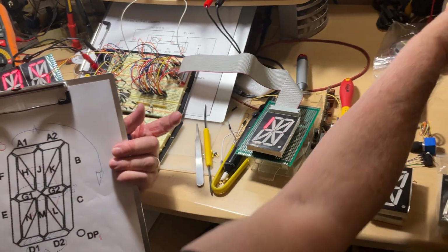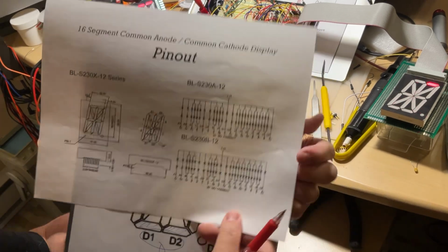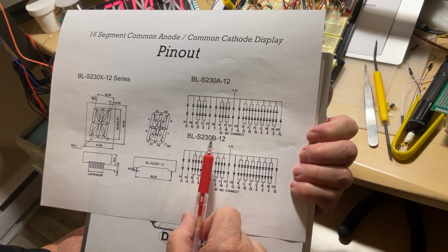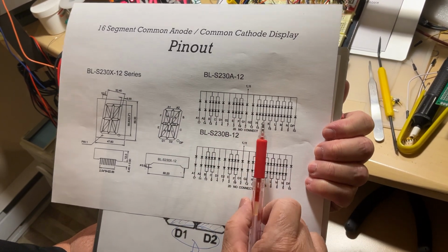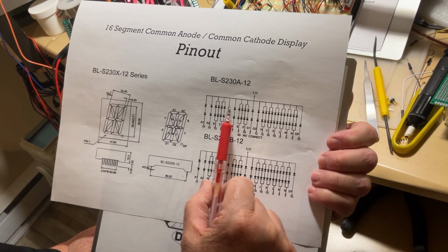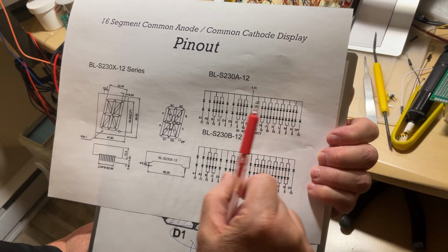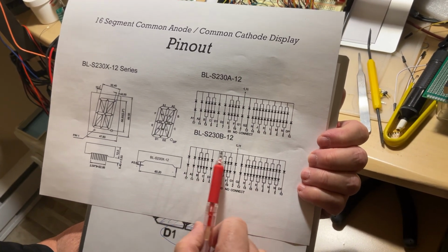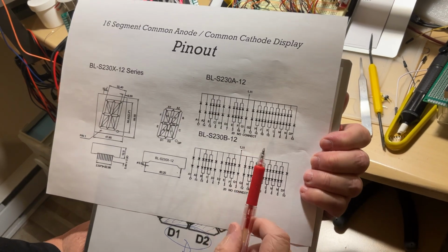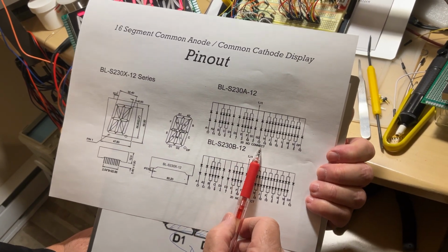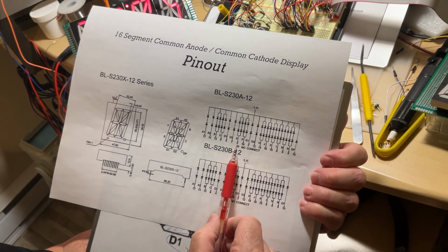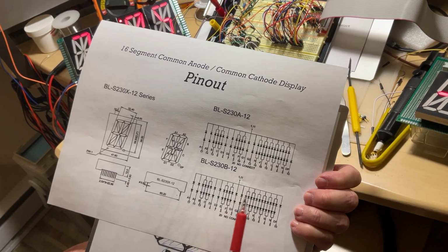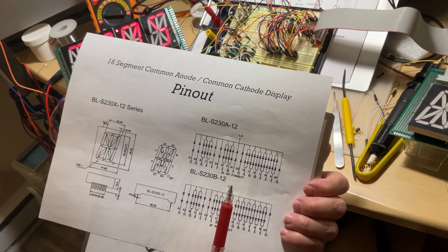And if I pick up the extract from the specifications, where the manufacturer gives us all the pin numbers, here, if you can see, all the cathodes are together. So this is the common cathode version. And here all the anodes are together. This is the common anode version. But the pin numbers are the same, and on both they say 20, no connect. Actually, they wanted to say pin 20 was not connected. So this is why pin 20 is missing, not because it's broken, but because they didn't put it there.